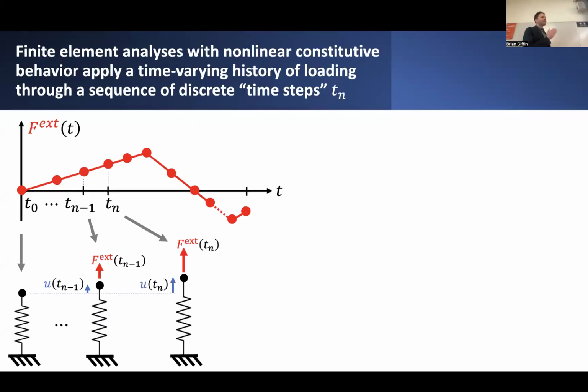All right, so first of all, we talked last week about nonlinear analysis. We said nonlinear analysis in general introduces a nonlinear relationship between the internal forces that result in some structure and the corresponding displacements at the nodes of that structure. But I want to point out that when we're considering problems where the relationship is no longer linear between forces and displacements, it can happen either in the case of geometric nonlinearities or material nonlinearities. In either case, the typical approach to solving these problems is not to simply take our structure and whatever loading we're going to put on it and apply it in one single step, going from zero loads to the fully loaded configuration. Oftentimes, that's not the preferred approach.